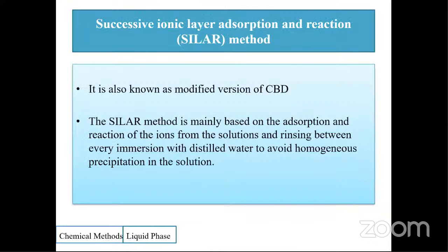Then the SILAR method, successive ionic layer adsorption and reaction, is basically the same type of thing, with only some modification made to the chemical bath deposition. The SILAR method is based on the adsorption and reaction of the ions from the solutions, and rinsing between every immersion with distilled water to avoid homogeneous precipitation in the solution.